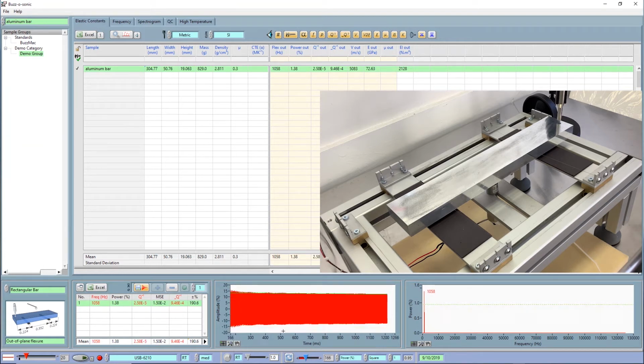When we offset it, we see now we can get a good fit to that curve. So now we get a value of internal friction, this Q to the minus 1. This mean squared error tells us how well this fits. As long as it's below 1, it's usually pretty good. And then this is the estimate from the half-peak broadband method. It's not accurate in this case because we've got very light damping, so we can pretty much ignore that.